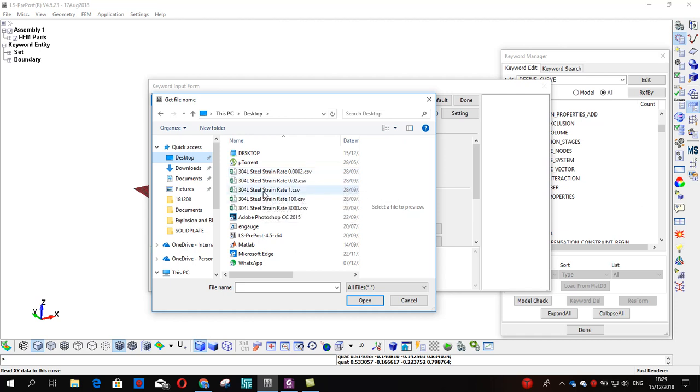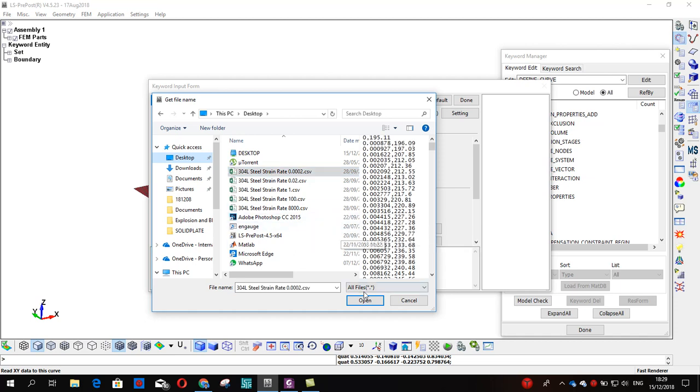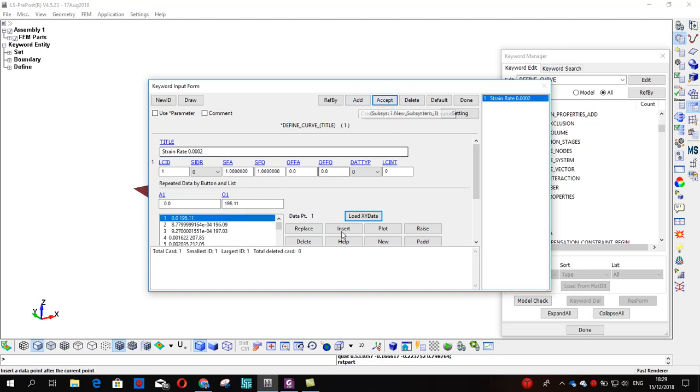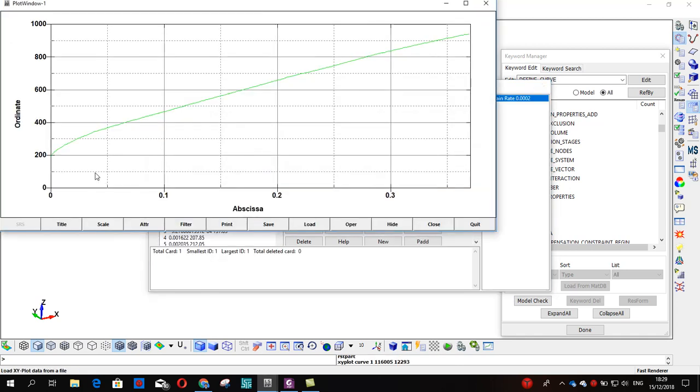I will give you the link in the description of this video so you can download all of these curves. So you go down here, you click on this one, open, and then you put in strain rate 0.0002 and accept. Now you have this one.